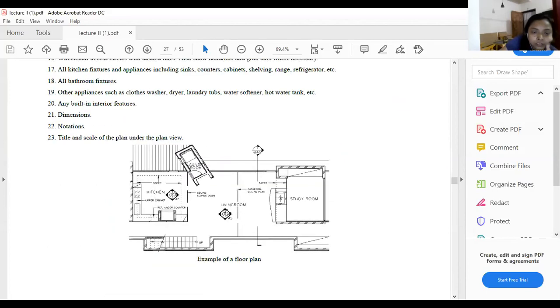See, this is the thing that I was talking about on the living room. This is the representation of your elevation. And see the thickness of walls. Suppose this wall is either made thick or it has been hatched. So this represents what? An external wall. Fine. And this is a thin line. This might be a glass, a fixed glass, which has been represented in a lighter form.